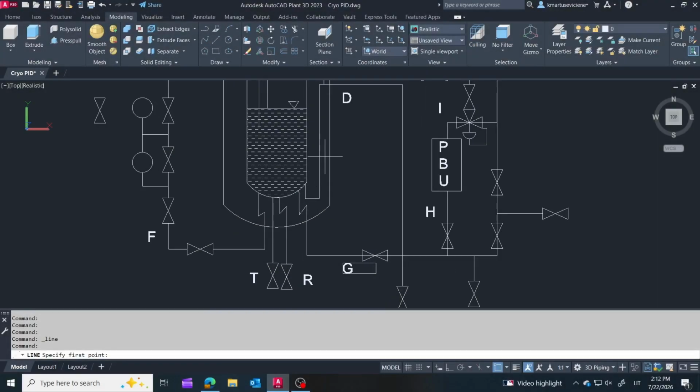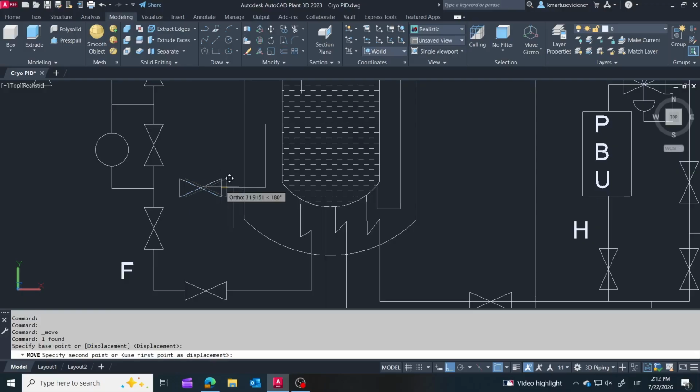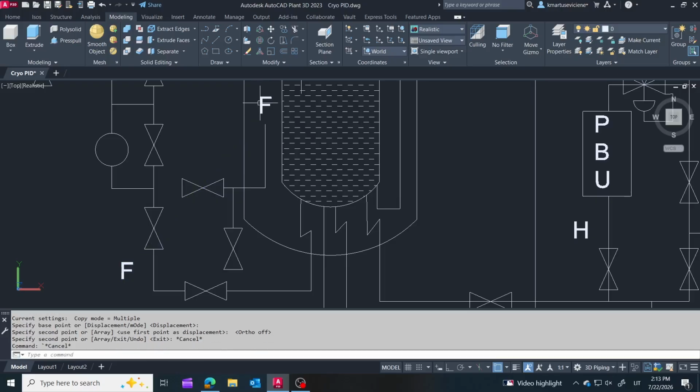The evacuation port is used to create and maintain the vacuum insulation around the inner vessel. Without this vacuum, heat transfer would increase significantly, resulting in much higher boil-off losses. Unlike the other nozzles we've added so far, this connection is not used to transport liquid or gas nitrogen. Its purpose is to preserve the thermal insulation that makes a cryogenic storage tank so efficient.